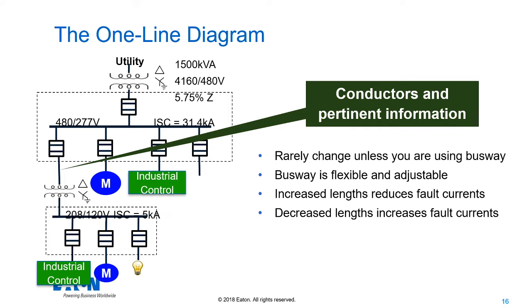Again, the length of those conductors is really critical when we are in the design phases. A single line diagram, which is another interesting point, we create even before we've purchased anything or installed anything. But when it comes to conductors, we may not know the length of the conductor until after it's installed, and these drawings should be updated. We should create an as-built drawing, which will document exactly how many conductors they put in phase with each other, what the length was, and all of that good stuff. Anything that may have changed from the design phase.